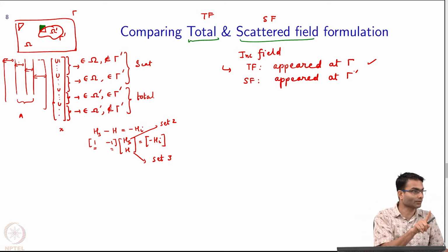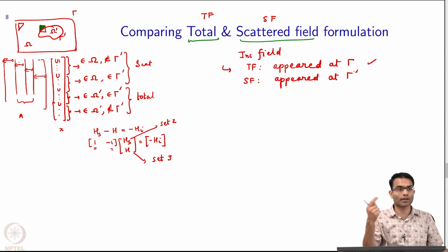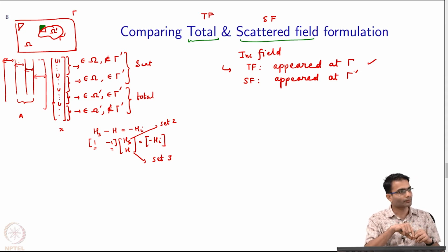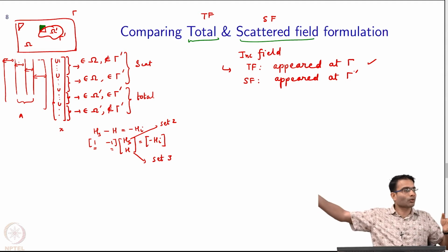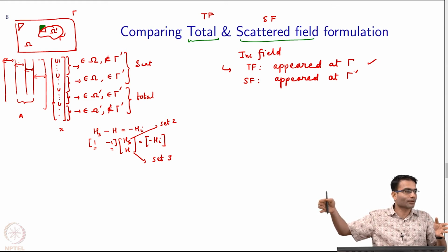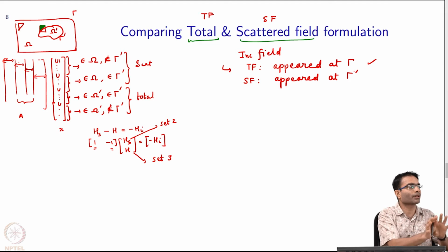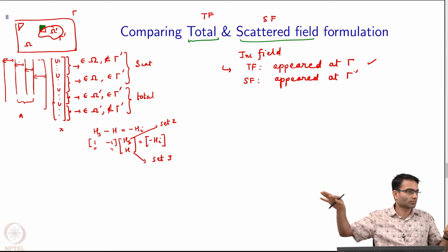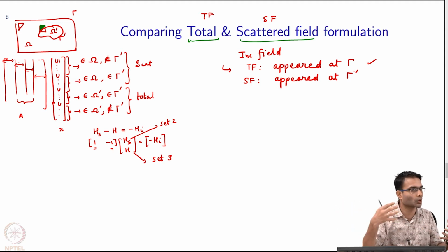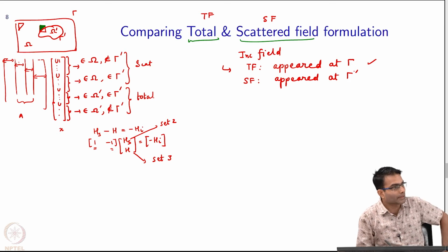And those triangles you saw, they were linear in x and y, but the actual field is what? Exponential, sine and cos. So, I am approximating sine and cos by linear functions in x and y. That approximation gets better and better as the size of the triangles is made smaller. Sin x becomes x, cos x, whatever other approximation you want to do. So, this approximation of the incident field on the mesh, is it more or less accurate as I go away from the source location? It is less accurate the farther I go away, because the errors will accumulate as I go further away, right? Very close to where I am specifying the boundary condition, it will be accurate, because the boundary condition is right there. Fields will try to match the boundary condition as much as possible. As I go further away, the error of the approximations will begin to grow, because I am finally trying to represent a sin and cos by linear terms, right.